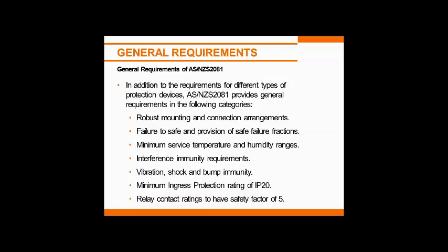The other thing called for is a minimum service temperature and humidity. Basically, the relays in the latest standard tend to head from 0 degrees to 60 degrees. And we fairly well test at all those levels, and while each relay may not individually be tested at those temperatures, there's certainly a preliminary test done to make sure the design is capable of working at those temperatures.